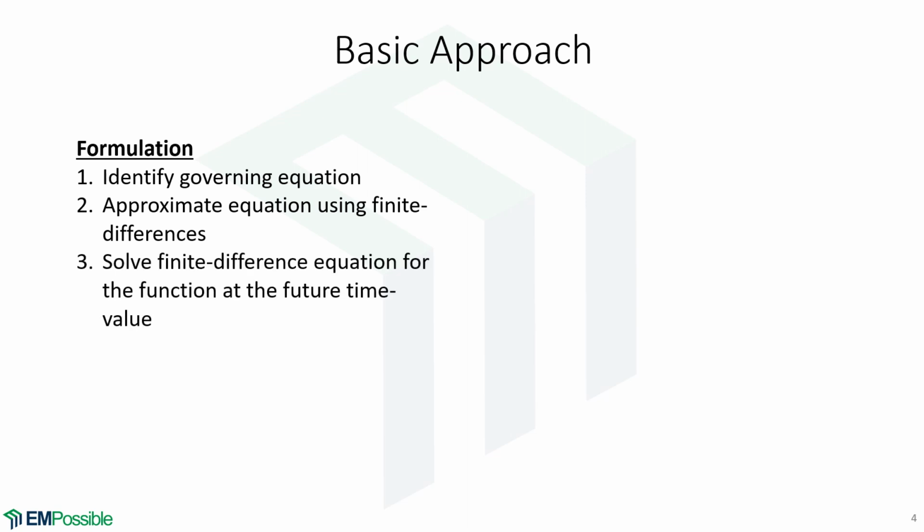When we approximate the time derivative with finite differences, we're going to get the difference of a new value minus a previous value. And there may be several occurrences of that new value in your finite difference equation. So what you'll do is you will solve that entire equation for that single variable, which is the new value of heat, for example. So you'll solve it for the future time step, we call it. In this equation, you may notice that a bunch of constants have collected. And those constants, if they don't change over time, you will want to calculate them before your main loop.